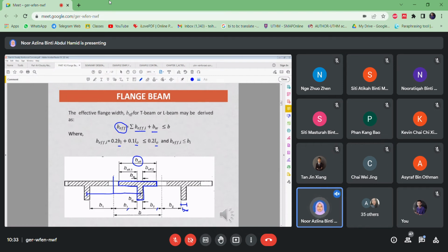half of it, and then you have to minus half of the BW. So this is the length, the clearance actually. B1 is from the center span to the surface of the beam. B2 also, you need to divide this span by 2, and then from the surface of the beam to the center span is B2. Okay, same goes to the other beam.